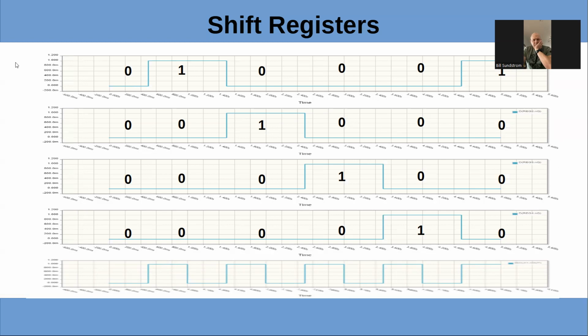The one place I was familiar with using these was doing encoding and decoding for radio control models. So you have a pulse train that's pulse width modulation, and they're in series. You would use the shift register to determine which channel was which as you shifted it through. You get each channel. It was real simple to implement. Takes 2 chips.